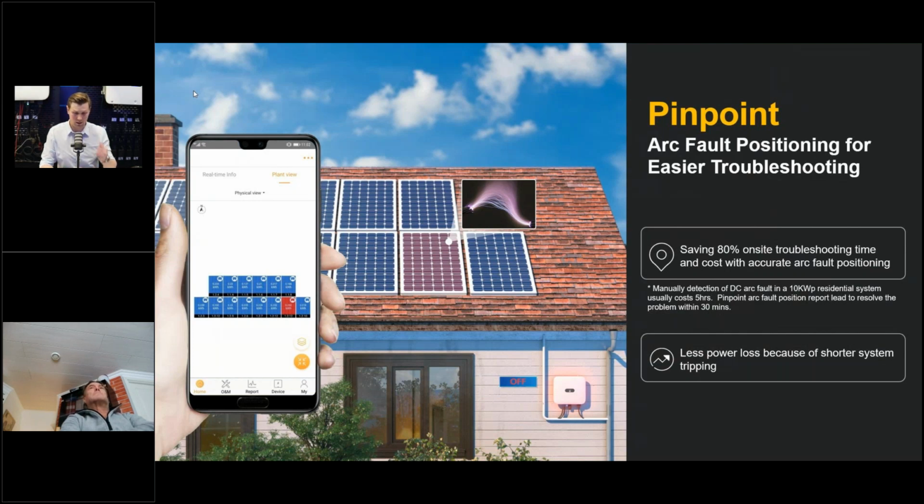So this function warns us that some arcing is visible on our PV generator and just turns off the inverter. If the situation repeats 5 times during the day, the inverter will recognize it as a very serious and dangerous situation and will switch off totally. And unfortunately, to reset it and make it work again will only be possible by going on site, finding the issue, fixing the problem and starting up the inverter again.